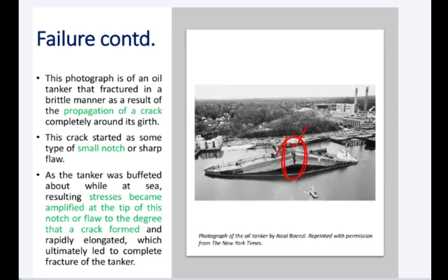Brittle fracture usually does not give you an alarm. It does not give you any clue that the structure is going to fail. You will not see necking. Suddenly it fails. So here there were cracks, and the cracks propagated. Keep in mind that all materials have microscopic cracks within them. It is not a flaw, but microscopic cracks are always available, and those cracks can propagate anytime due to stress. So while designing a system, we have to take care and keep in mind that there are microscopic cracks.